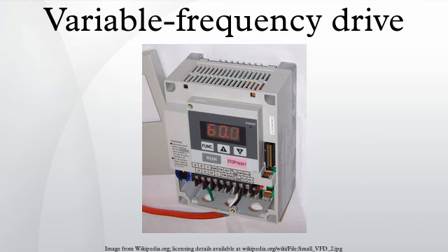The following table compares AC and DC drives according to certain key parameters. High-frequency injection, VFD types and ratings, generic topologies. AC drives can be classified according to the following generic topologies: voltage source inverter drive topologies. In a VSI drive, the DC output of the diode bridge converter stores energy in the capacitor bus to supply stiff voltage input to the inverter. The vast majority of drives are VSI type with PWM voltage output.